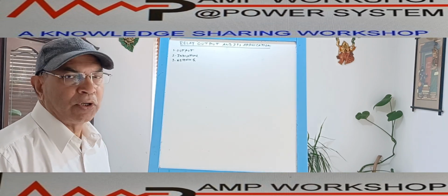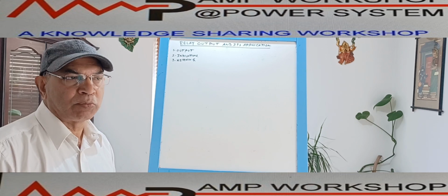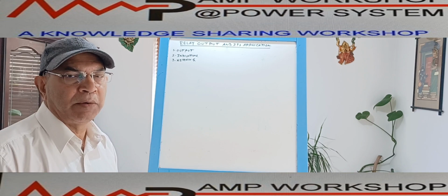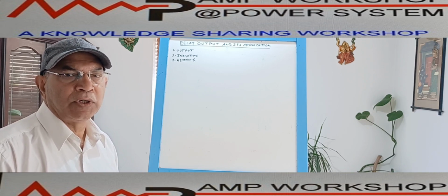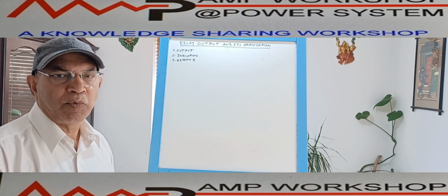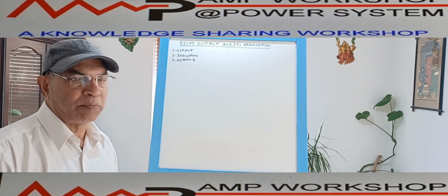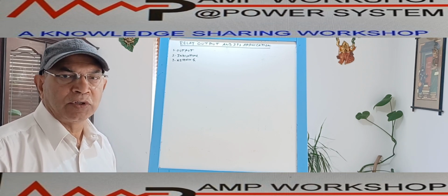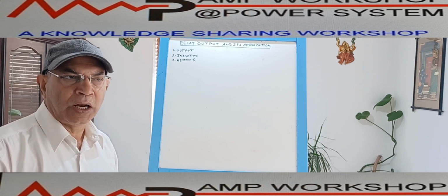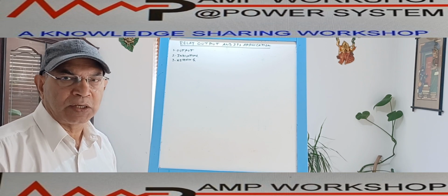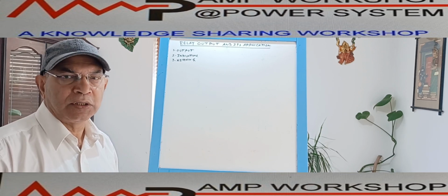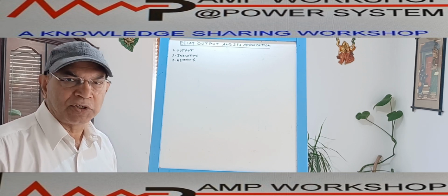In this video, we'll also try to cover two other small aspects. One is the various LED indication lamps available on the protection relays and how we can assign them for various functions. The other is another important feature of intelligent protection relays. In addition to protection functions, control and interlocks, which we discussed in previous videos, the protection relay has metering features.